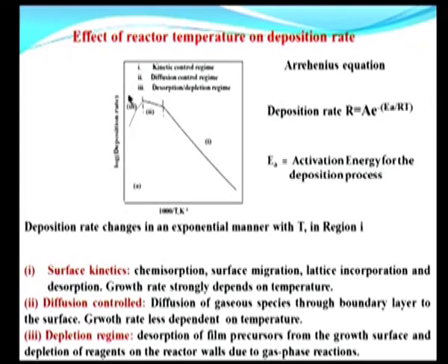At a middle range of temperatures, the growth rate is essentially independent of temperature. So, this is the region where one would like to operate the CVD process, where the growth rate is relatively insensitive to temperature.